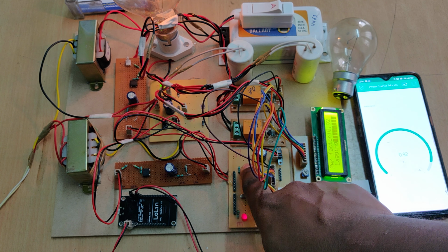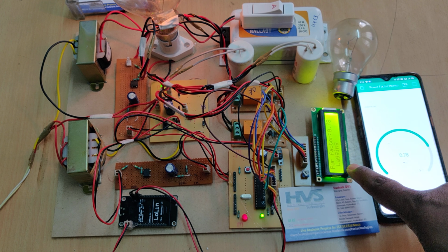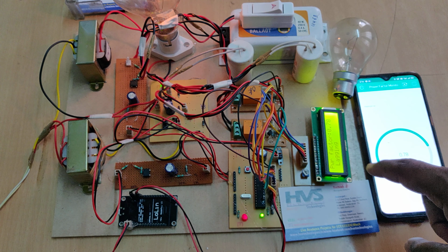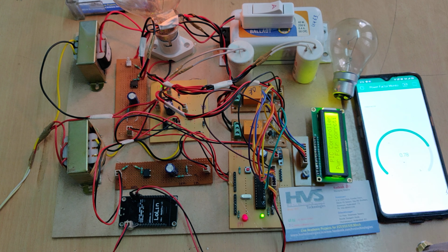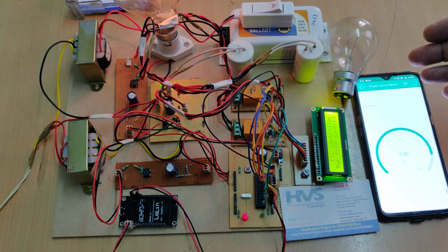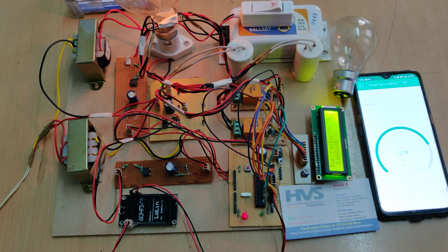If there is a malfunction, you can just restart this. The relay has already switched on, and now it's lagging. You can hear the sound, and because of the relay back EMF, the microcontroller is restarting, but it will settle down. Now gradually the power factor will increase. Right, it's 0.86 now, and again it will switch on the second relay also. Right, and after that it will settle down.